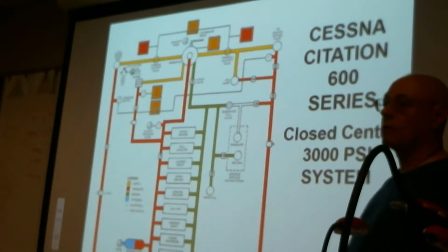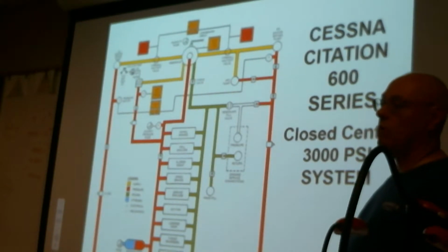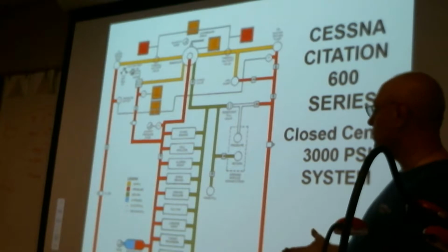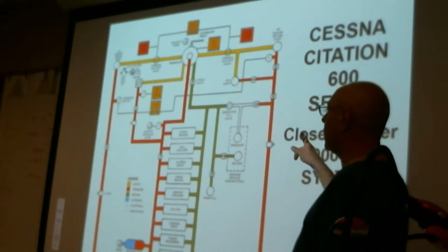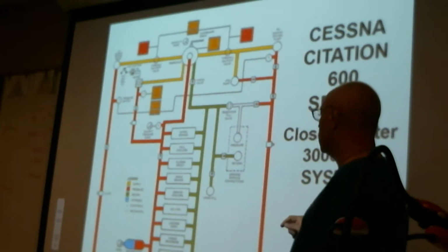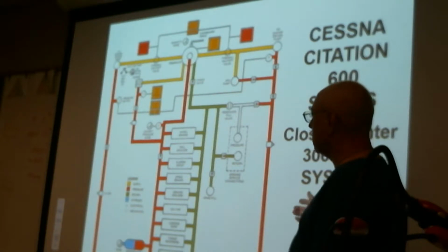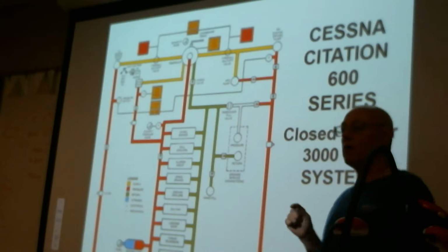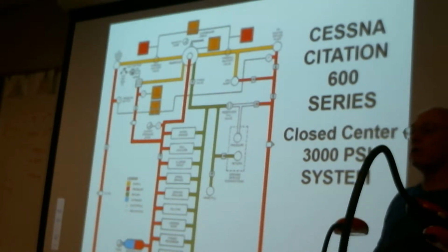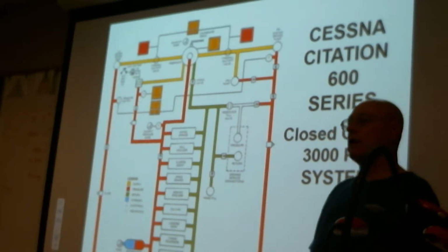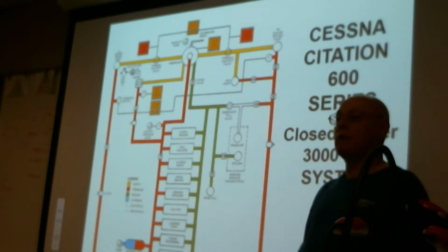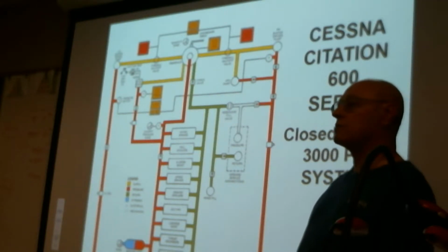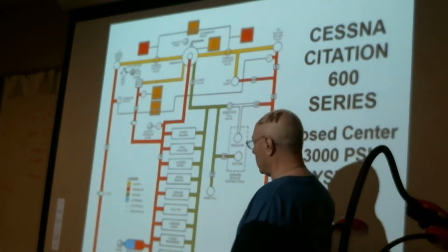We're going to have to be able to operate multiple components at any given time. So we need to use a closed center system. What does that mean? It means that you're going to have to have pressure regulation in the circuit. It's more complication than you normally have. One thing I want to point out: if you were to look at a schematic, without looking at too much other than what's in the schematic, and trying to figure out if you're dealing with an open center system or a closed center system, look at the component here.